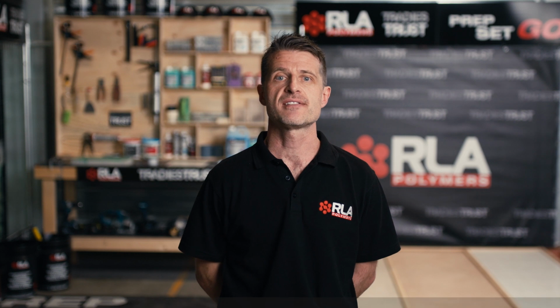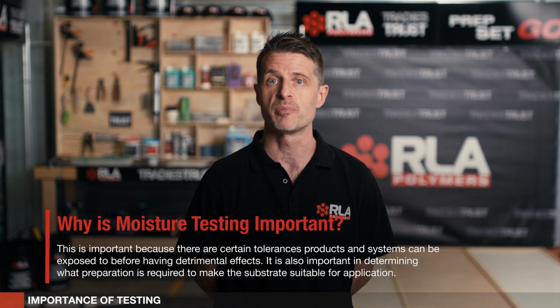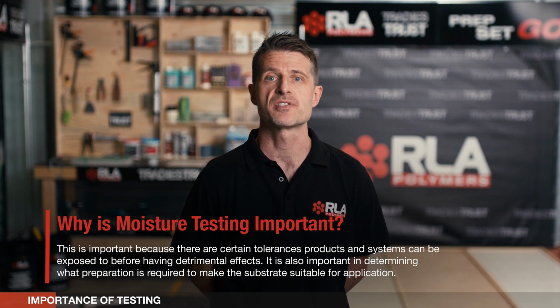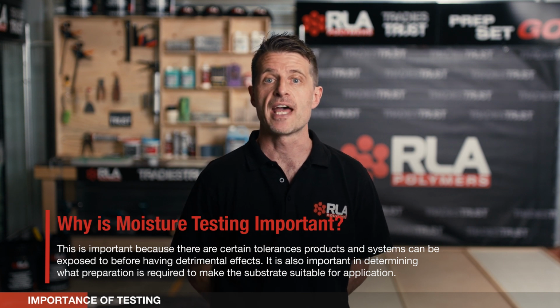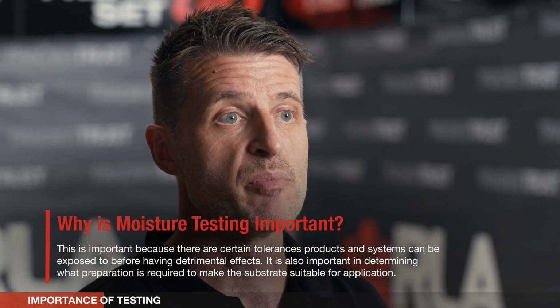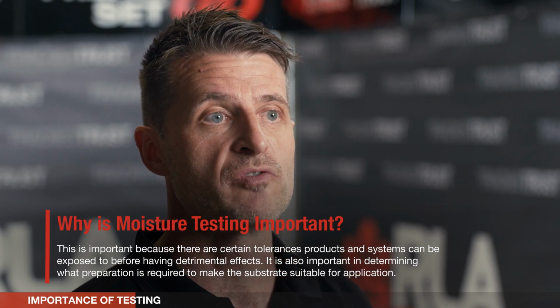Now the importance of testing. Why is moisture testing of a substrate important before applying our coatings and floor finishes? Well, testing is important because there are certain tolerances products and systems can be exposed to before they have a detrimental effect. It's also important as it will determine the preparation required to make the substrate suitable for application. And there are a number of standards relating to different floor finishes and coatings that specify the maximum allowable moisture content in concrete that they can be applied to.